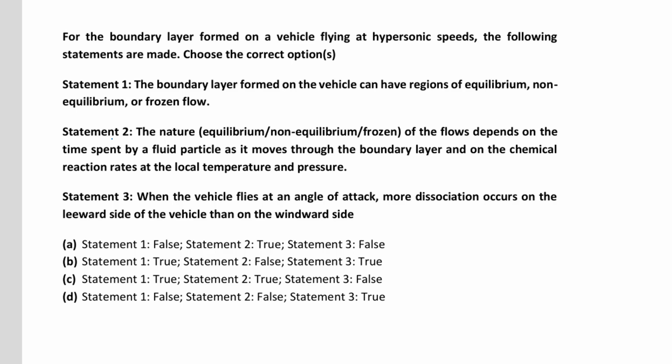Statement 2: The nature, equilibrium, non-equilibrium, or frozen, of the flows depends on the time spent by the fluid particle as it moves through the boundary layer, and on the chemical reaction rates at a local temperature and pressure. Statement 3: When the vehicle flies at an angle of attack, more dissociation occurs on the leeward side of the vehicle than on the windward side.